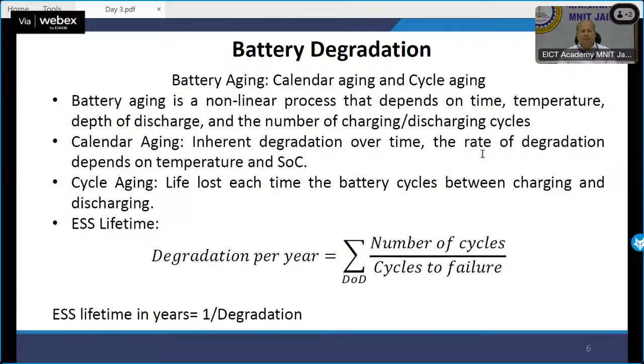They will simply say the warranty and guarantee depend on the cycles that you have performed. So you may get the battery for, let's say, a period of 5 years. They assume that you will charge and discharge only once in a complete day. But now you are doing 100 charging-discharging cycles in a day. So then certainly the life cannot be 5 years.